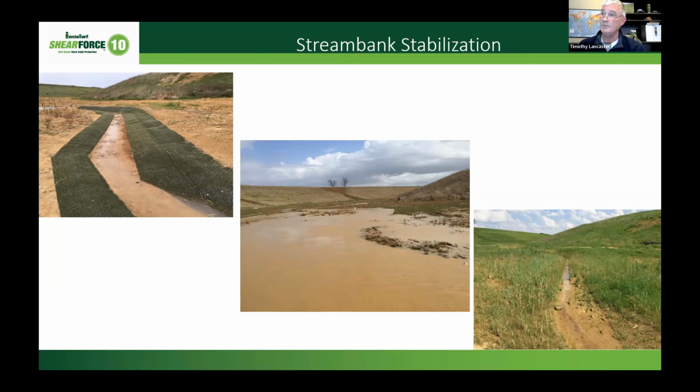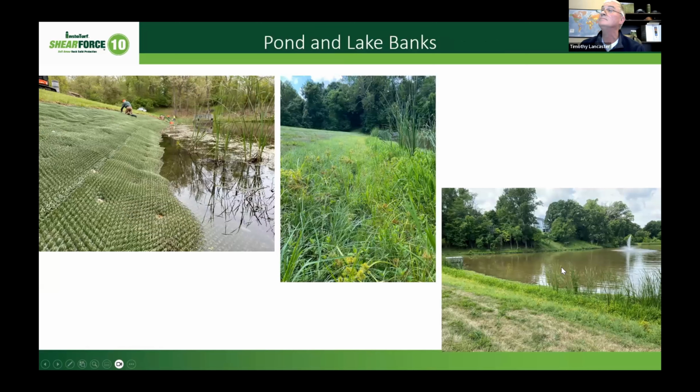And it's good they did, because that winter in particular, they had hardly any snowfall in that area, but they had a lot of rain. They kept getting these 2-inch storms coming December, January, and February. Every time that would happen, that little stream channel would flood out. And then you can see in the picture to the right there, really good vegetation growth right along the bank where the matting was used. And see some real distinct lines at the toe there, and that's right where the matting stops. So it's kind of like right where the matting stops is where the vegetation stops.